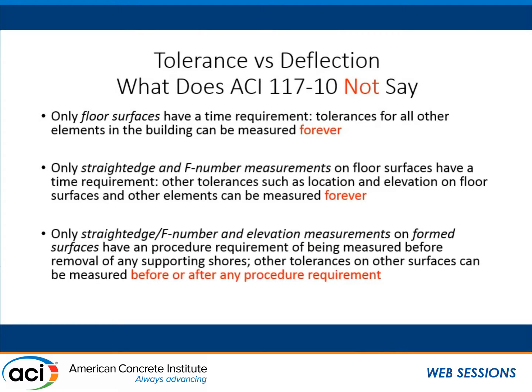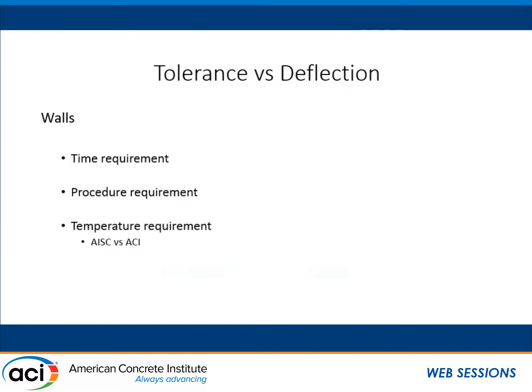But we don't. So I think we may need to look at our timing and think about more than just floor surfaces, and think about our procedural requirements and think about more than just removing the shores as an issue. So if we look at tolerance versus deflection, we're going to look at some wall issues. So is there a time requirement on walls? No. Is there any procedure requirement on walls? No. What about a temperature requirement?